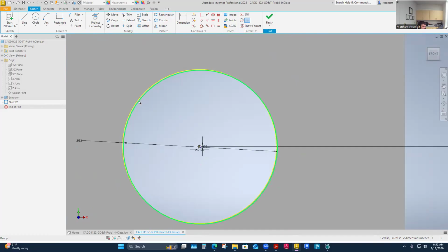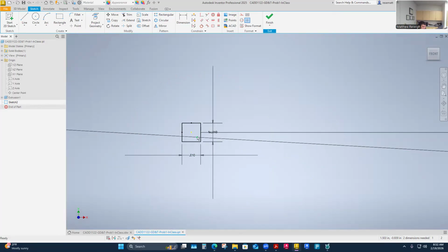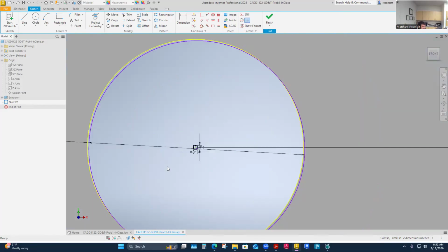This is how I've modeled it. This is what my tolerances are saying, that I would be okay if my circle lived where that purple circle is right now, because it's in my tolerance zone. The center of it lives in the tolerance zone. Even if it lies on that, it's still going to be within the tolerance zone.